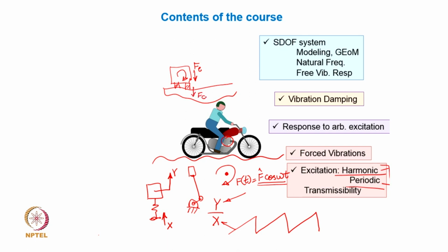Okay. And if we want our mounts to be efficient and effective in reducing the forces which actually excite the chassis to vibrate, we would like these mounts to be designed in such a way that only a fraction of the excitation force from the engine gets transmitted to the chassis. So, the ratio F e over F c in this case becomes the force transmissibility.